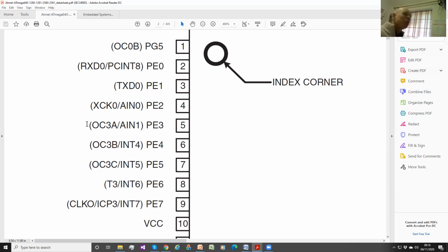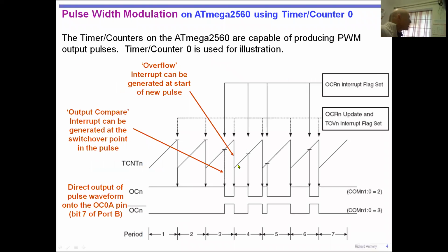Do you remember we looked at that table of alternate functions for the port pins? These output compare functions are the alternate functions of several different pins on the chip. As I say, there are many spread around the chip, but these three, because they're all clustered together and they're all on port 3, are a nice example to focus on. Now let's go back to this slide.